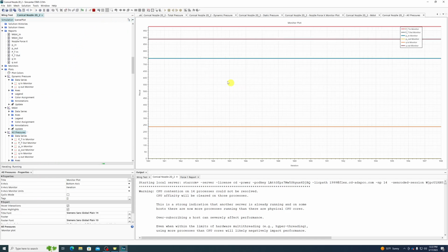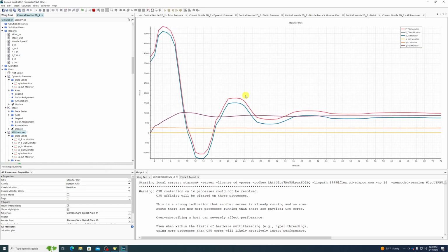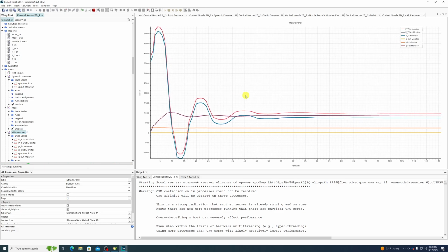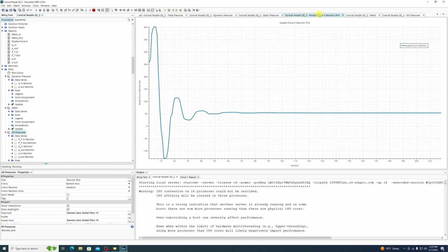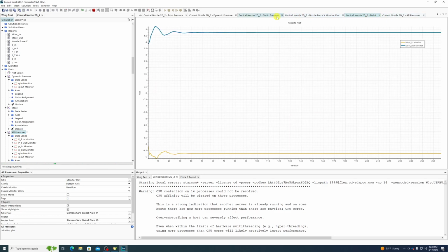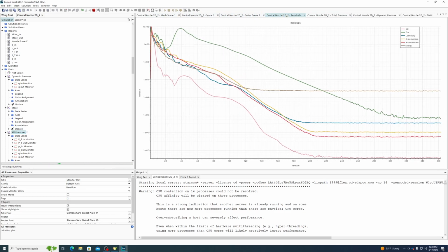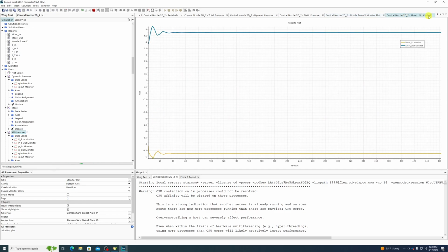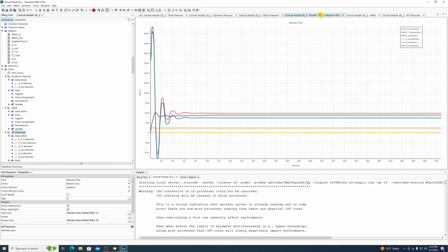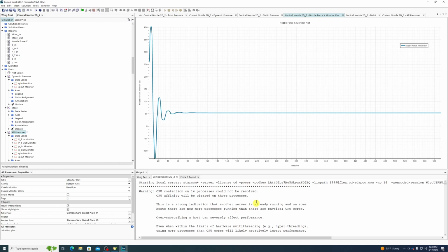Okay, hit run. And even better yet, this runs fast enough. We're going to clear the solution just so we can see how these change from the beginning. Oh yeah, this converges real fast, doesn't it? It's not quite not changing at all, but it's mostly not changing. Let's see here. Dynamic pressure, total pressure. Residuals. Okay, residuals are now flatlining. This is pretty much considered converged at this point, I would think. M dot. Oh, that's our force right here. Yeah, this is pretty much rock solidly converged.